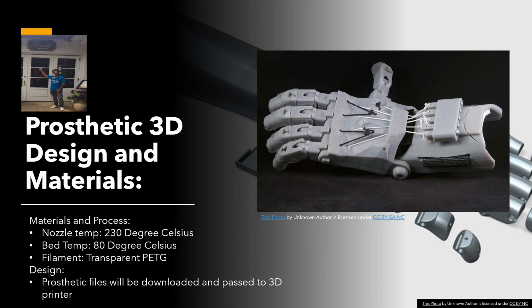Upon the completion of the 3D parts, it will go down to assembling. The fingers will be connected to the palm, which will then be attached to the arm that will house the motors. These motors will be tugging on a fishing line, which will provide the closing of the fingers, and a separate rubbery line that will bring back the fingers once the motors are not pulling on them.